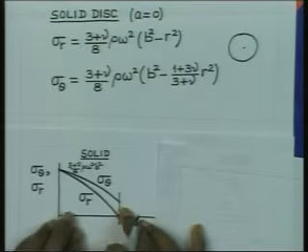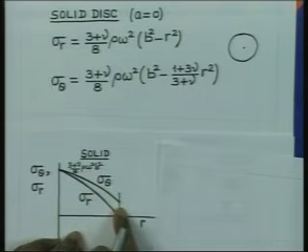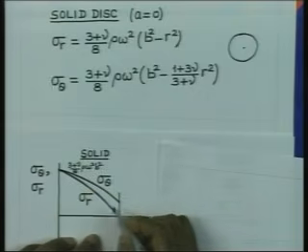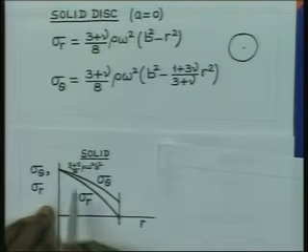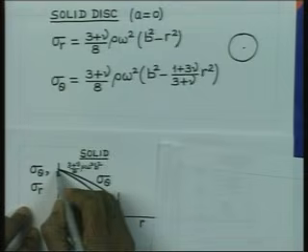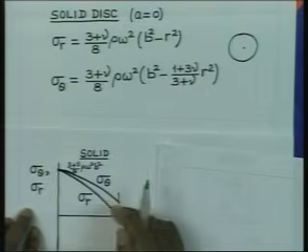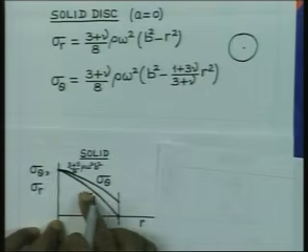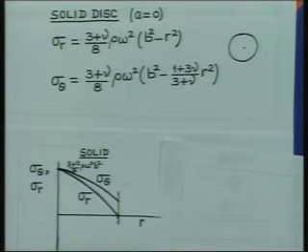And the radial stress is 0 at the outer radius, and the sigma theta stress is going to be higher than that. So, this is the value here. Look at this slope, it is going to have 0 slope at this point, and it is gradually going to have negative, increasing slope. So, both the variations are going to be given by this.